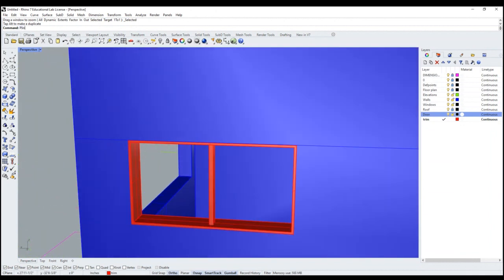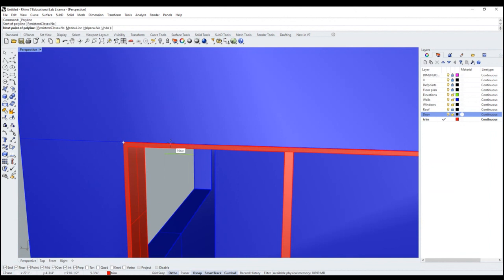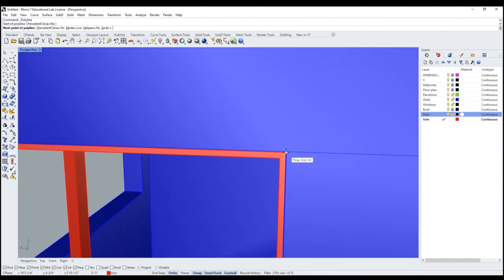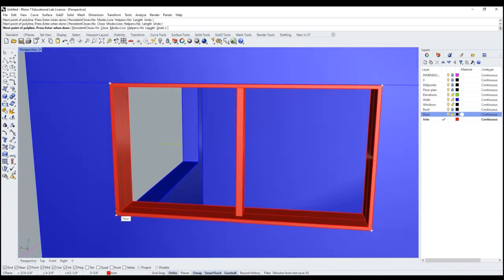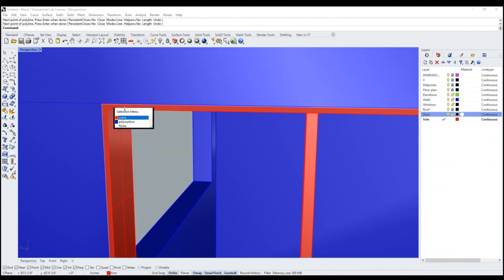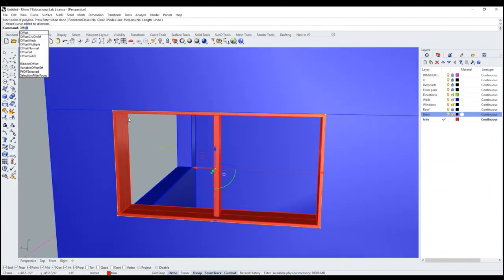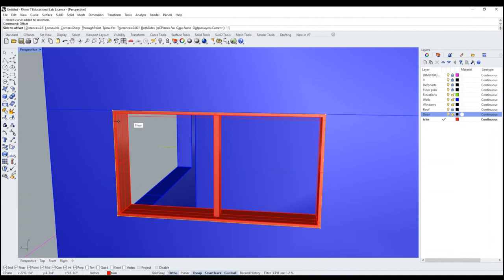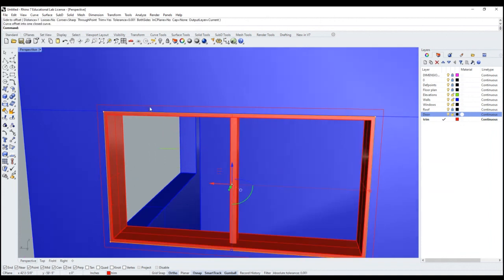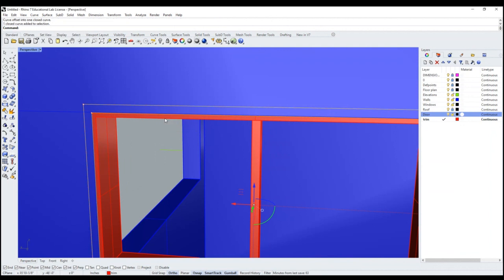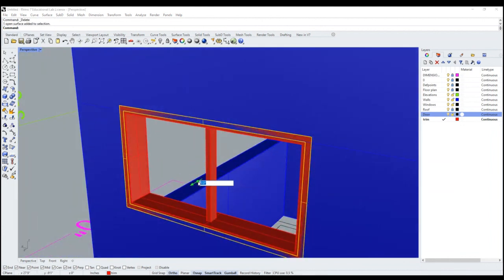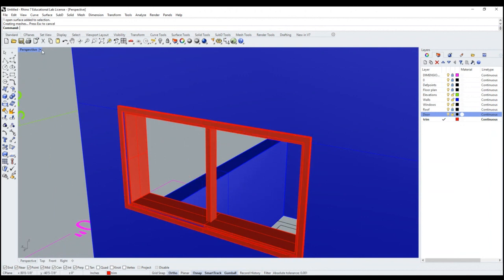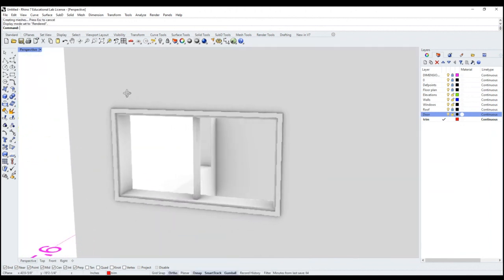And then now we can make our trim. But this time we're going to offset on the outside 1 inch, just like the rest of them. Grab our other curve, planar surface, delete the curve, grab the surface, and it's gonna come out 1/2 inch. And so this is what our window's looking like right now.